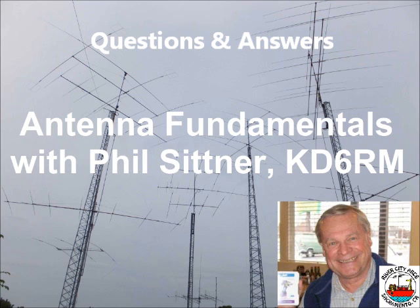You can put what's called a gamma match on the element, and there's a whole series of different types of matches. There are what are called coaxial stubs, which are pieces of coax that you can use to perform this match. There's no shortage of ways to perform a match.